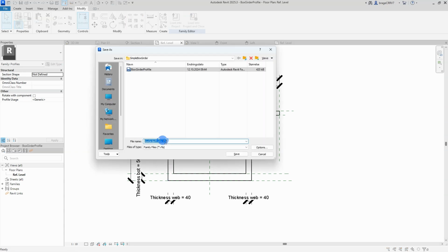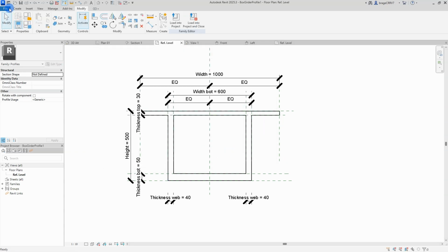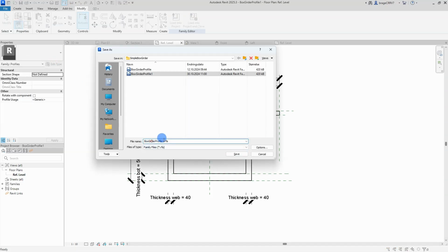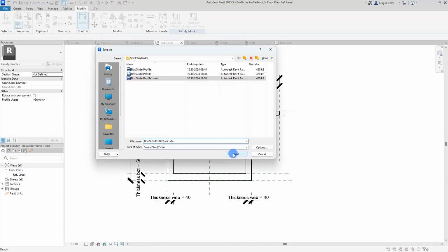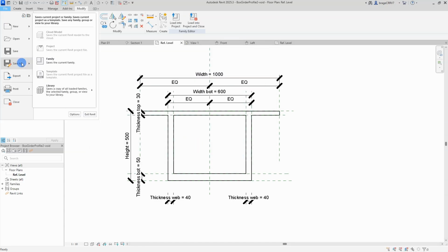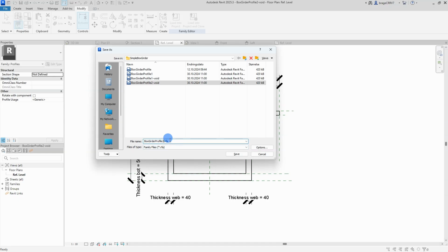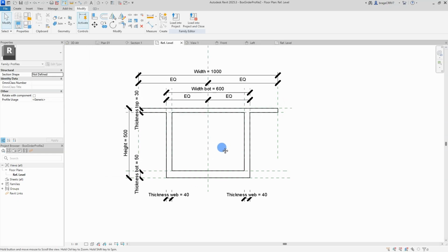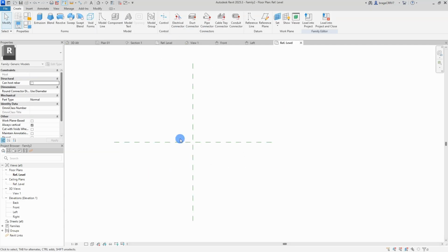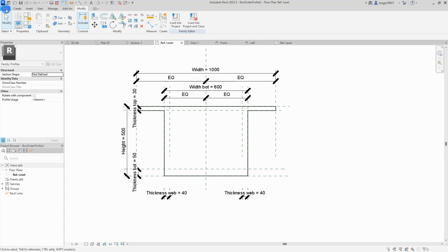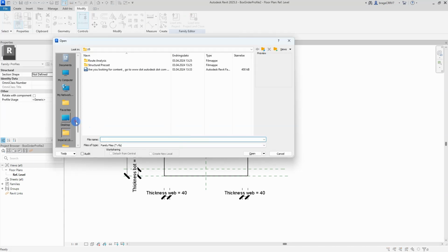Since the 2D parametric family I created in the last video is already created, I'll be reusing it here rather than starting from scratch. For this project, we'll need a total of 4 profiles, 2 for the solid geometry, to achieve different cross-section shapes at the start and end of the sweep in the parent family, and 2 for the void geometry. Note that we need separate void profiles to avoid errors when sweeping profiles with holes. Go ahead and save these metric profiles before loading them into the host family.